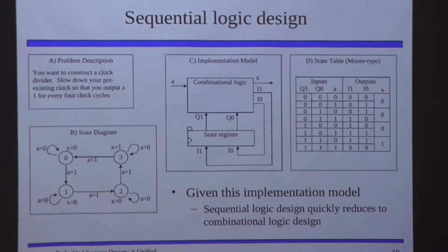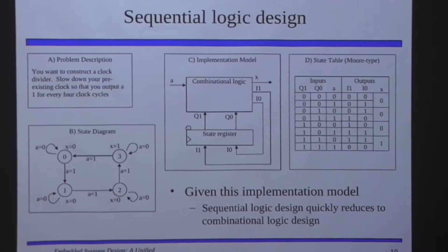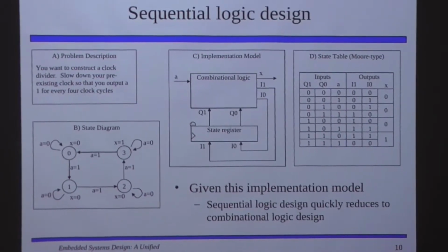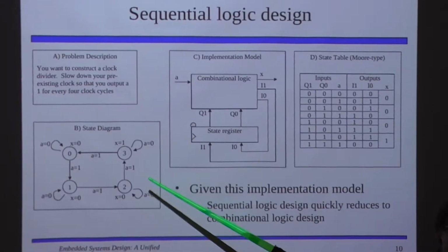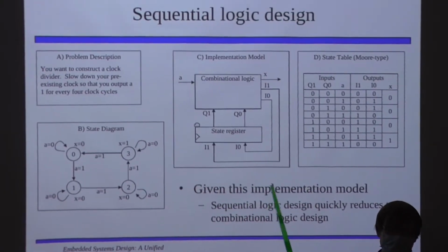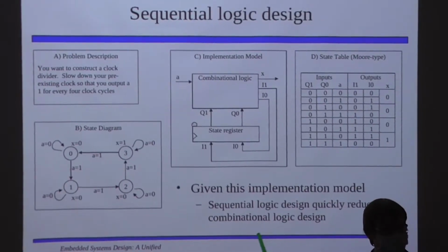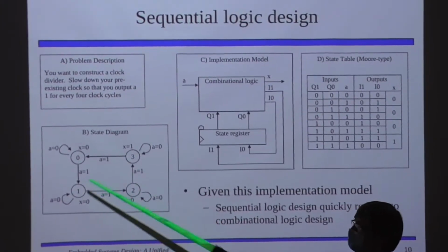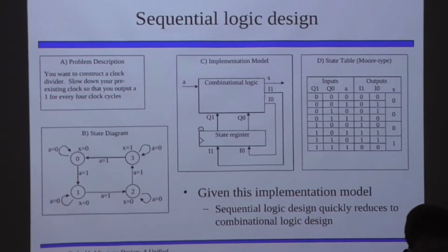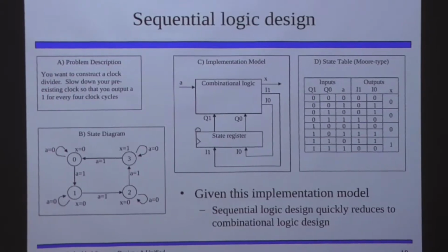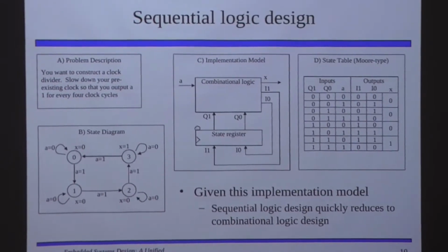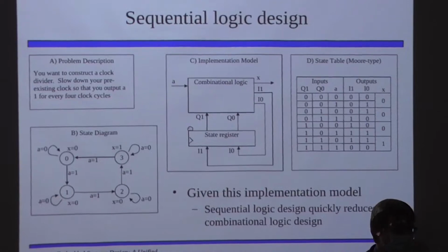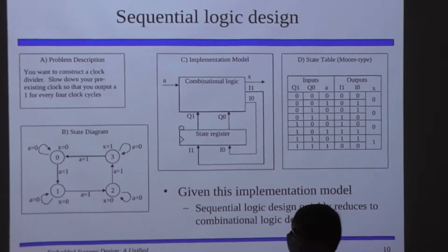not the real-time clock. The timer module from earlier in the course, right? We had that prescaler module. We're going to explore what the logic inside of that thing actually would look like. But we're also going to simplify it so that, rather than have 8 or 16 bits inside of that prescaler value register, we will have 2 bits inside of that register. The prescaler value will be fixed at 4, but we have a counter register inside of the prescaler that is counting between these 4 different values, up to 3, starting at 0.